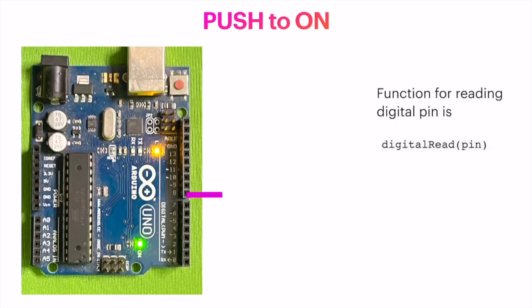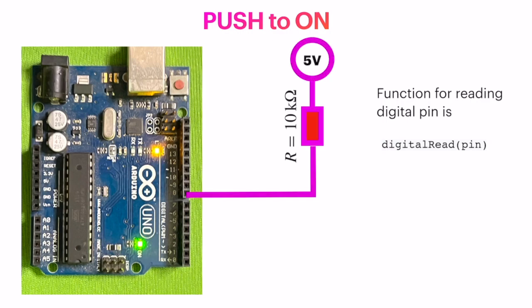So what we do is we connect this pin number 8 directly to the 5 volts with a reasonably large resistance, that is about 10 kilo ohms. This 10 kilo ohms is usually not low enough to make it a ground state. That means that even if you connect pin 8 through a 10 kilo ohm resistance, digitalRead would still give you an output of high.